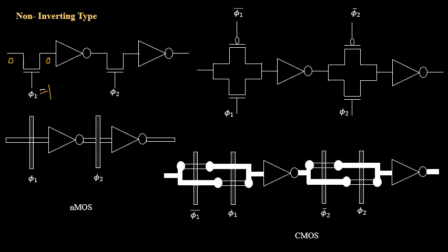Here it is an inverter, so when it is passed through an inverter, it will give the reverse, that is 1. Suppose I make this signal also equal to 1 in the next cycle, then 1 is going to appear towards the output side of the NMOS transistor, second stage. 1, if it is passed through an NMOS inverter, is going to yield us an output of 0 state. If you see here, I had applied the data input as 0 and I am going to read the value also as logical 0, which is performing this non-inverting operation.